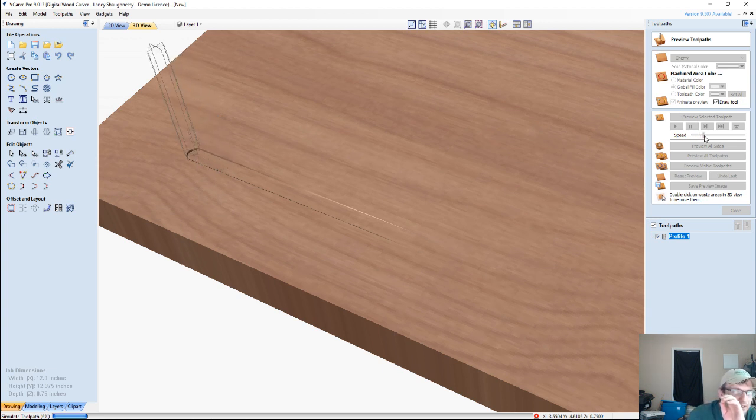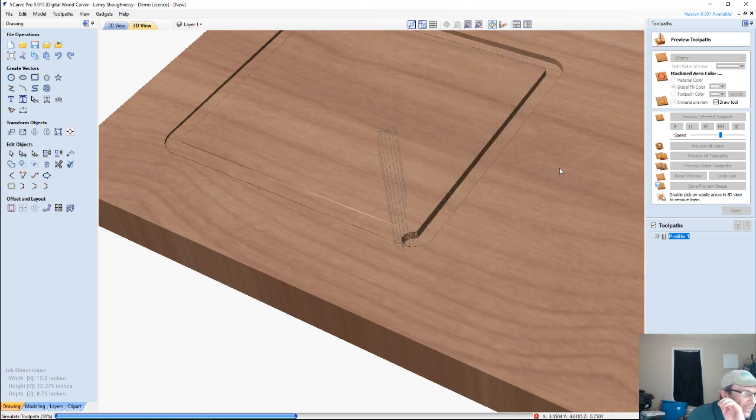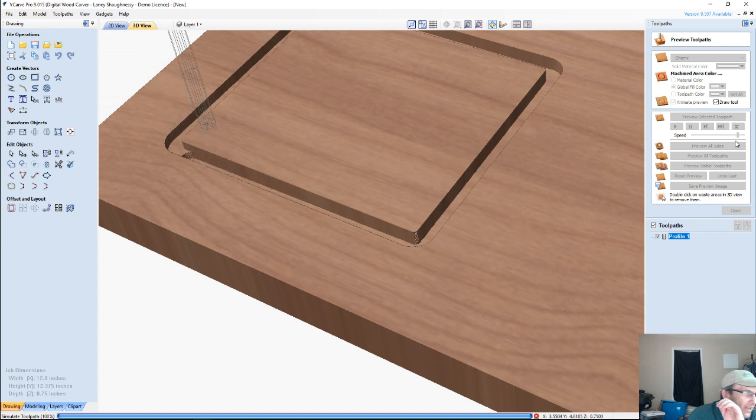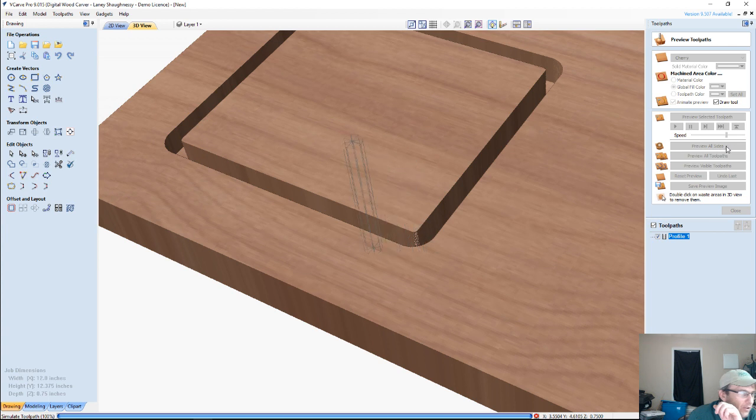And if I speed it up just a little bit, as it makes the turn, it's going to get deeper, and it's going to continue taking that little depth, that little ramp, all the way around until it gets down to its final pass. And when you're doing a spiral toolpath, if you ever watch your Z box and your absolute measurements, you'll see that Z just continuously dropping. So a spiral toolpath,